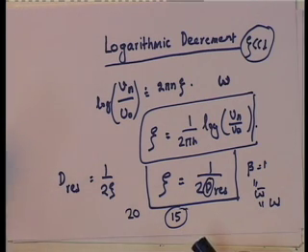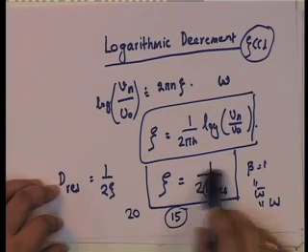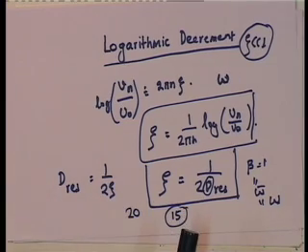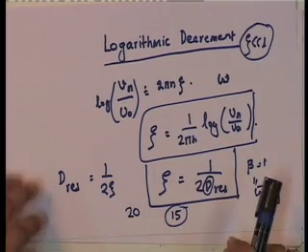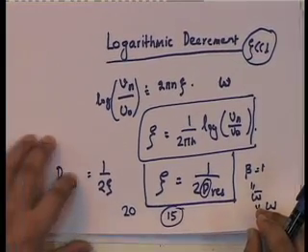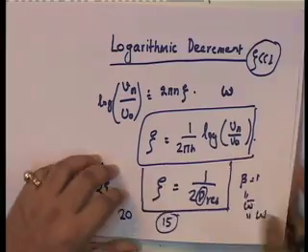You have almost a 33% error in the estimation of xi, purely because you could not exactly get the value at resonance. So, both these methods, although in principle they are very good, in reality they are not very good, and that is the reason why we tend to use what is known as the half power bandwidth method.